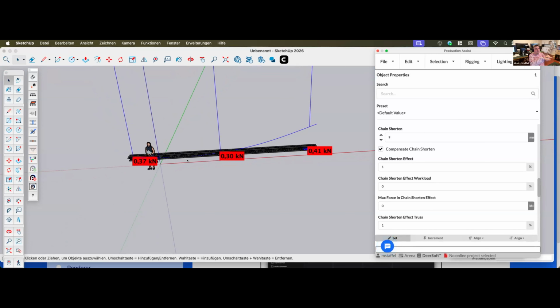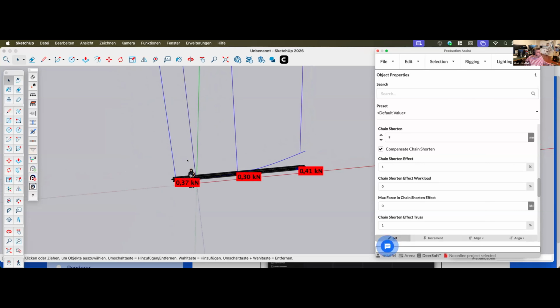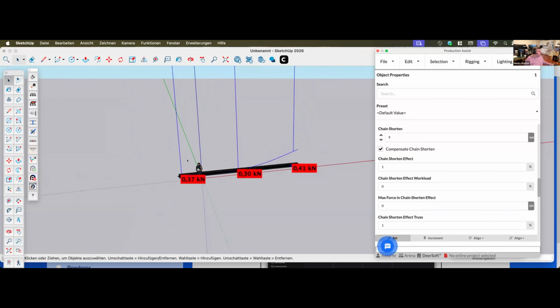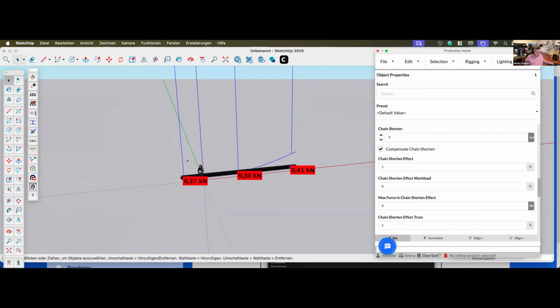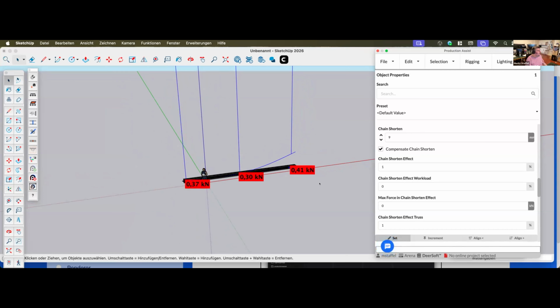So if you don't make sure that they are all on the same level, you will basically have different calculation results. It is easier to mess it up with hoists, but it basically also applies to the standing frames. You can also hang the AluVision frame, so that's also something important to know. That the chain shorten, or basically the leveling, has a big impact on the actual calculation and changes the reaction forces, for example on motors, but also the workload quite a lot.